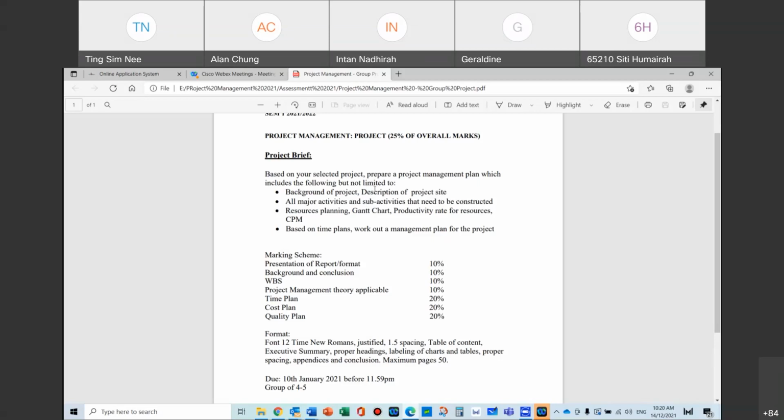And then you add all the major layers, ending up with one subtotal, meaning that the third layer adds up to the second layer cost, and the second layer adds up to the first layer cost. So let's say pipeline works will have one cost, okay? But you've got to show us how you do it, okay? And then you just have to add up, and that will be the final cost of construction for your project, whether it's a civil project or a structural project, or civil combined with structure, that's fine.